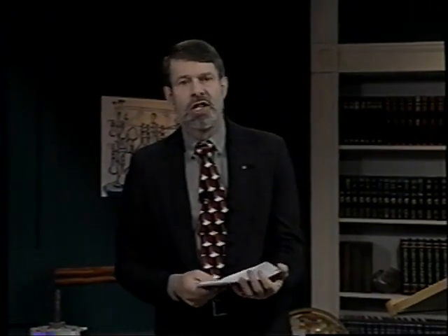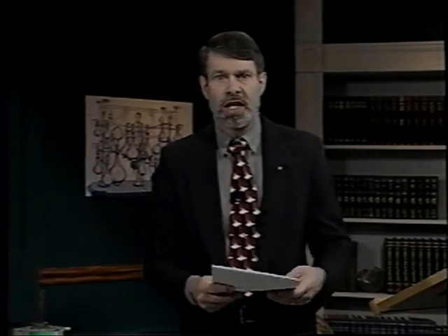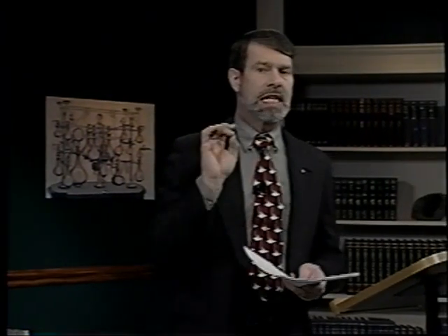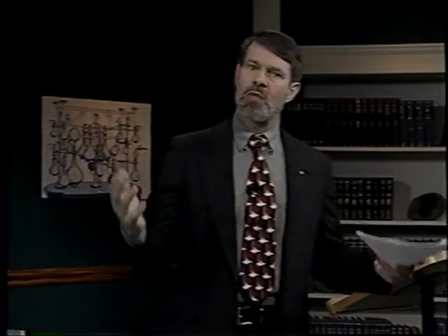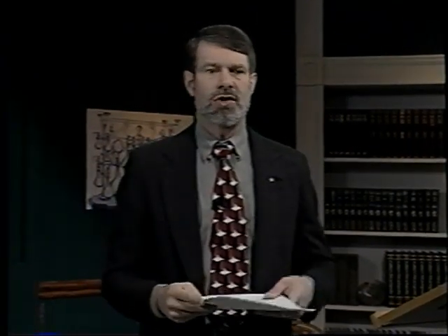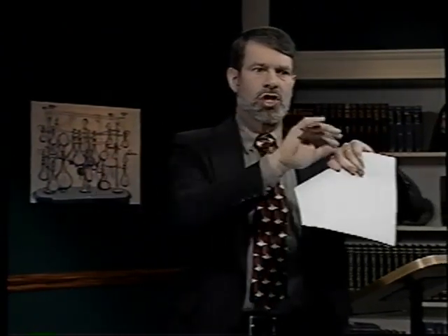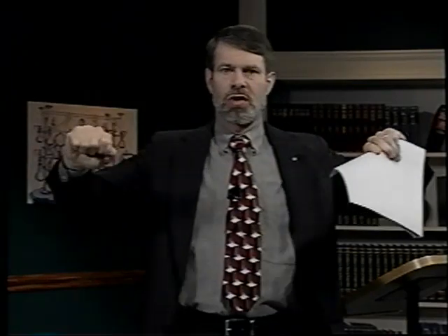In the last lecture, we surveyed many of the properties of materials. And I examined 5 of those properties and showed that each of them was in some way related to the atoms and how those atoms are bonded together. For example, we talked about the strength of materials. We had compressive strength. When you squeeze a material, how strong is it? We have tensile strength. When you pull on a material, how strong is it? For example, a rope, a chain of atoms that are linked strongly together, is a very strong material under tension.